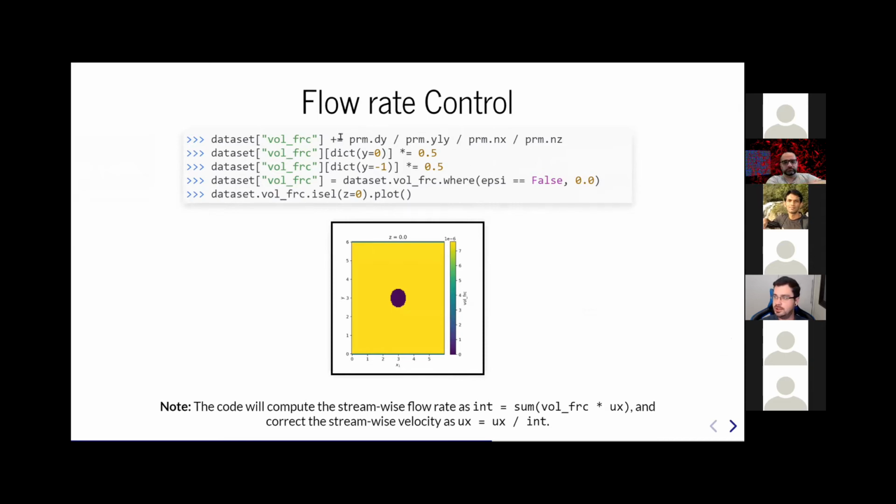And this one here will compute the vertical integration and will give us a unitary value per height unit, besides including an average in X and Z. We multiply both top and bottom planes by half because of the composed trapezoidal rule for integration. And of course, we remove the geometry from our integration operator.